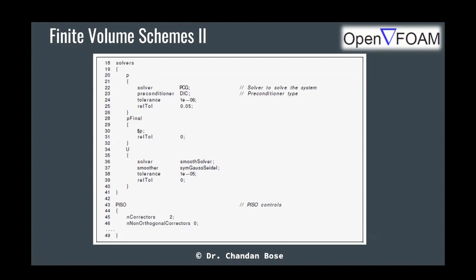In these given solution files, there is a class name dictionary I have seen everywhere, but you don't understand the implication of this class. Where? What is the class? In the dictionary. Any of these files are called dictionary, right? The dictionary file to create a mesh is called blockMeshDict. The dict means dictionary, right? Creating dynamic meshing is called dynamicMeshDict because it's a dictionary file.